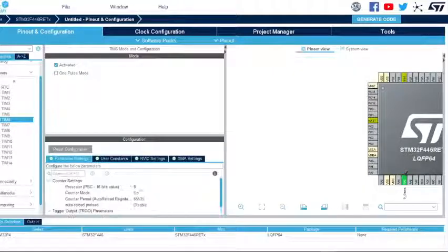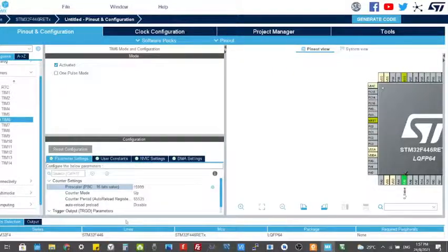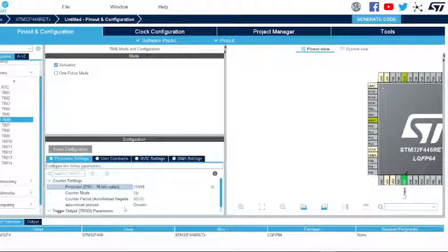And our prescaler is again 15,099. Basically, there's the calculation there in the datasheet. I won't explore on that one too much. And here is the loaded 65535. It's basically the max counter period, because again the timer 6 is a 16-bit timer register.